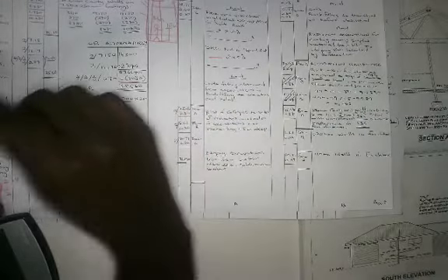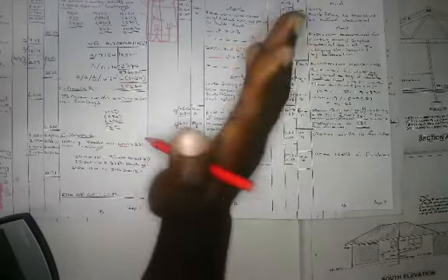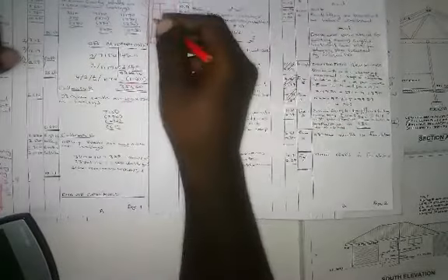And then we need to do risk of collapse. As I was saying to you, we need to protect our workmen, so we need to protect the sides of our excavation so that it must not collapse. We need to put mechanisms, either machinery or timber materials, to make sure that if we've got an open trench like this, the soil doesn't collapse and then the person in the middle gets buried.